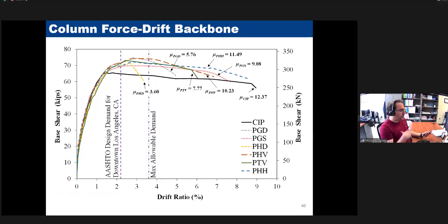However, if you put this column in California, in downtown Los Angeles, the maximum displacement that you expect to see under design level earthquake is 2.2 inches, 2.3 inches, while this column achieved 3.5 inches of displacement. So it still is okay, but it's not in the realm that you feel comfortable with.